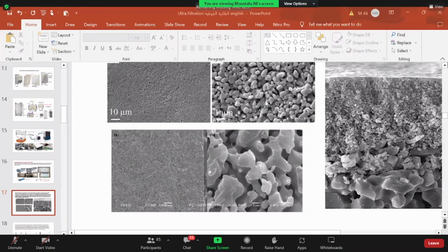In the case of silicon carbide, we can form this layer easily just by making a mud solution. This mud solution is made from very tiny silicon carbide particles, 1 micron. It is an almost liquid, very muddy, slimy solution. We take the plate and just put it inside the solution and take it out.